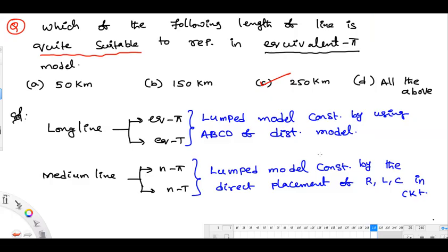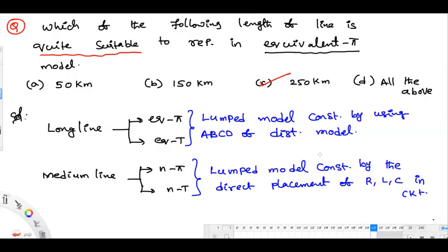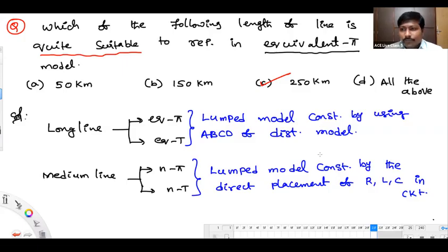Means from this formula we are getting that, as an extension. Yes, but that is not the original one. You should not say the change in voltage from no load to full load. As a definition, we should say the rise in the voltage when the load is suddenly thrown off.